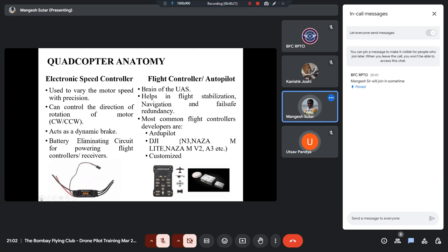And then you can recognize it by the color of the strobe lights also. You will always see the front strobe lights are green and the back strobe lights are red. But the best way is to see the flight controller, if you are able to see it in bigger drones, more of the industrial drones, or the GPS. Most of the time the drone will be fitted with the FPV camera, the first person view camera. Whenever you see that camera in the front, that is the heading, the front view of the drone.